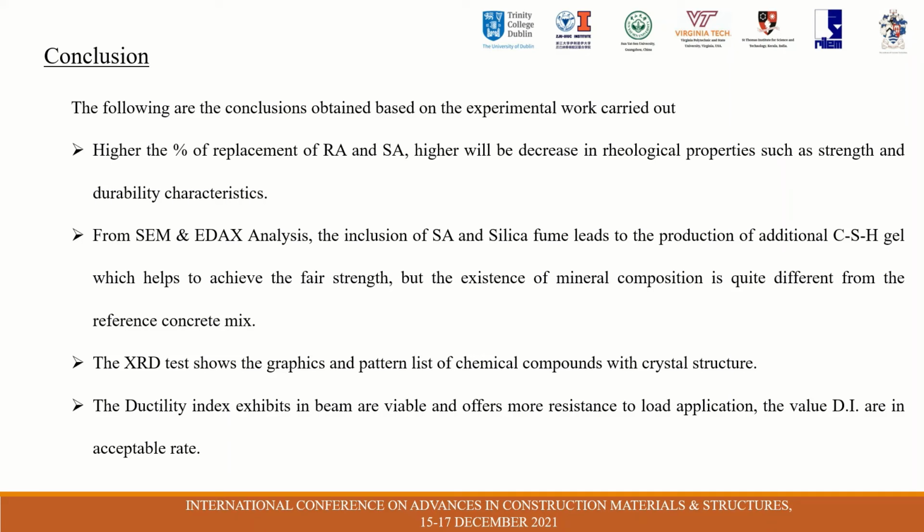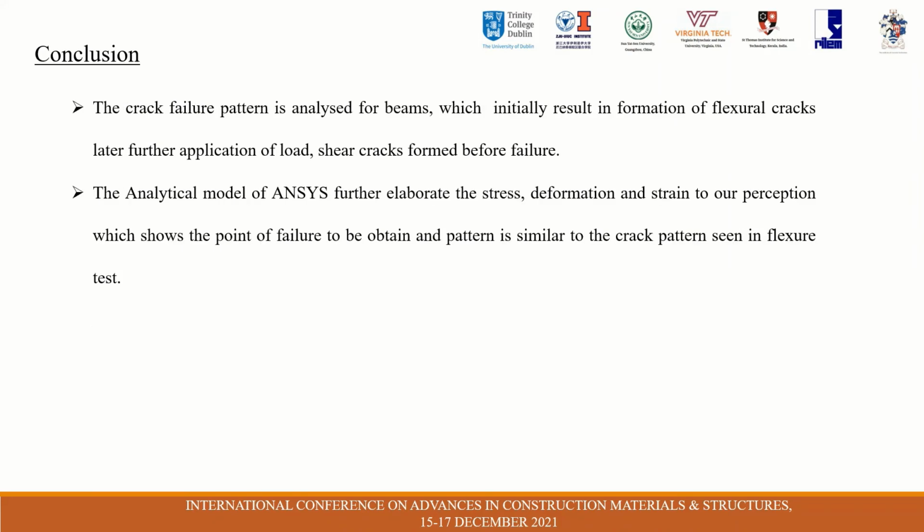The XRD test shows the graphs and pattern list of chemical compounds with their crystal structures. The ductility index exhibited by the beams is viable and offers more resistance to load applications. The value of the ductility index is at an acceptable rate. The crack failure pattern was analyzed for the beams, which initially results in the formation of flexural cracks. Later, with further application of loads, shear cracks form before the failure.